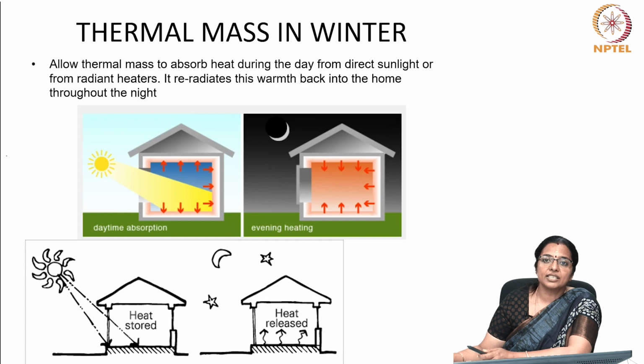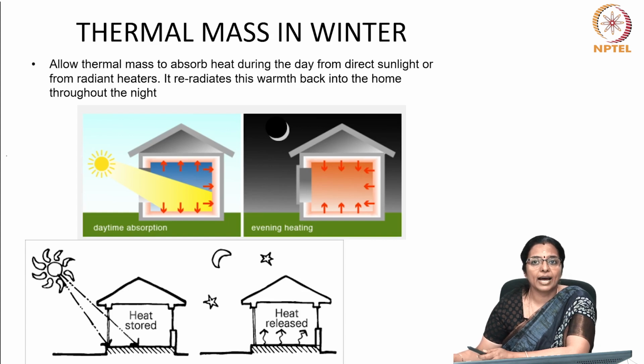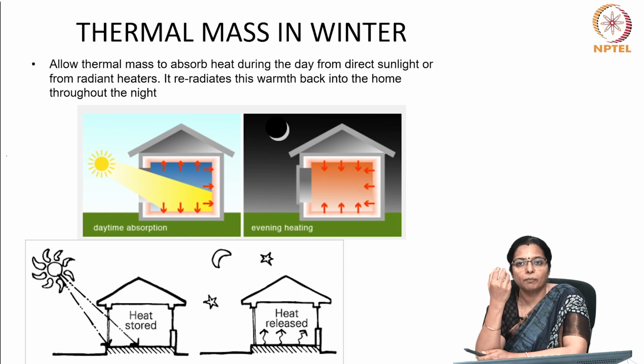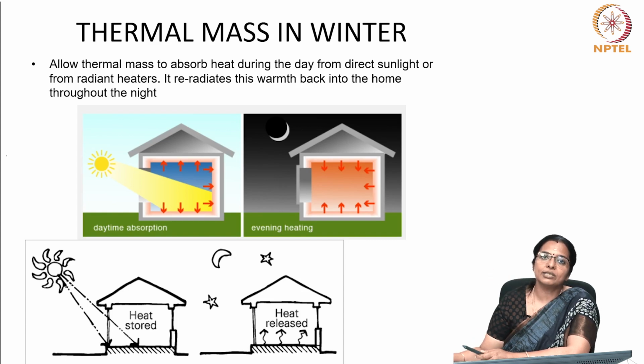Because thermal mass distinguishes itself as a tool for dampening of temperature amplitudes, it works best when excessive heat builds up and requires absorption and much later disposal. For example, where the excessive heat generated by solar gain is absorbed by the building fabric during daylight hours, or where a particular environment has excess heat which is generated by the people who stay inside and absorbed by emission into a cooler nighttime space.